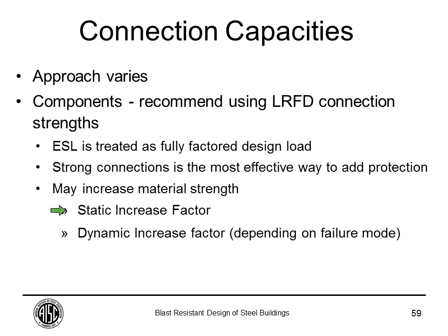If you're looking at something brittle and sudden, kind of like a shear on a weld or shear through a plate or bolts, you probably don't want to use your DIF. If somehow you have a connection where you're bending a leg of a plate or something like that, where it's more of a bending kind of behavior, you may actually use the DIF to gain a little bit of strength on your connection design.